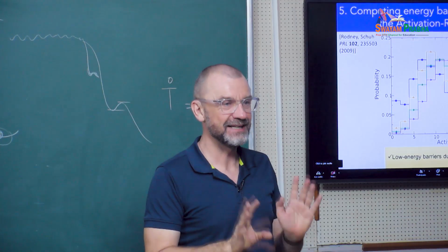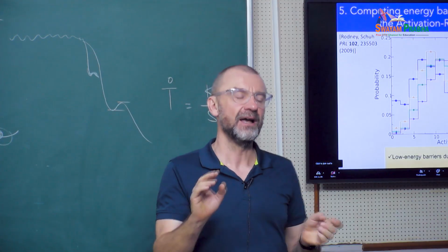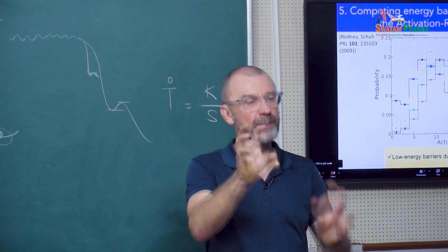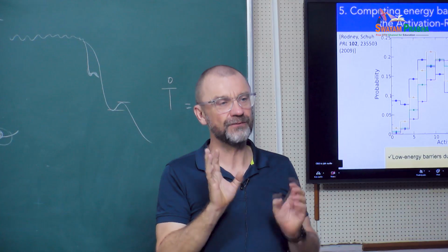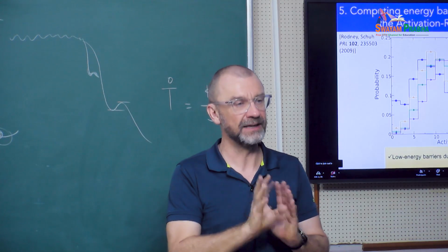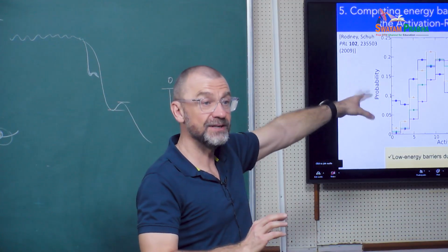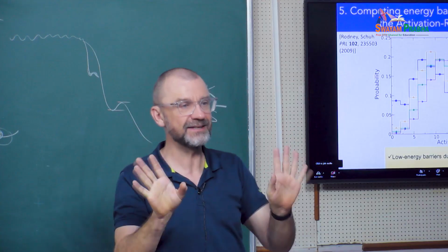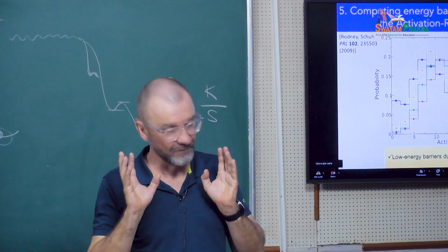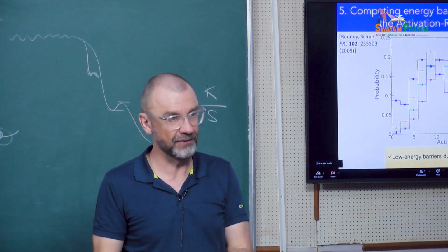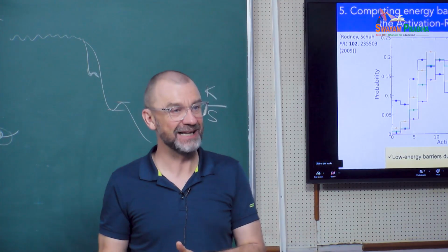For numerical glasses, some progress has been made these past few years mixing swap Monte Carlo and molecular dynamics. It works very well, but for very specific interatomic potentials, not these binary systems here. So for binary systems or ternary systems, realistic glasses, we are still doing these quenches very fast, which means that the glasses that we have in our computers are always far less relaxed than real glasses.